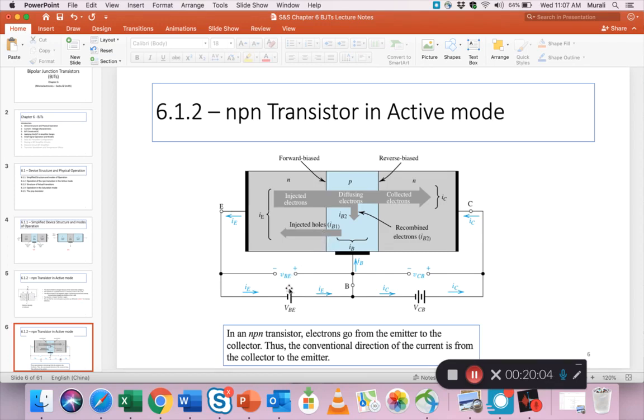When you apply a forward bias, we know there is a cut-in voltage for a semiconductor junction to begin to conduct. The small vBE is about the actual voltage across the junction itself, while the external voltage is shown with a capital VBE. So just remember that difference.